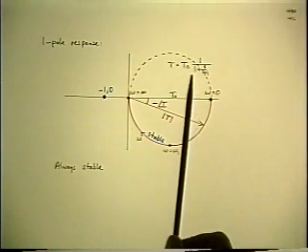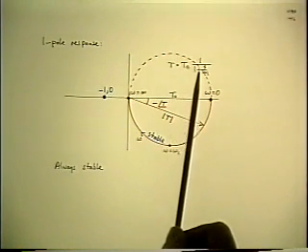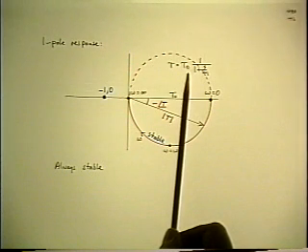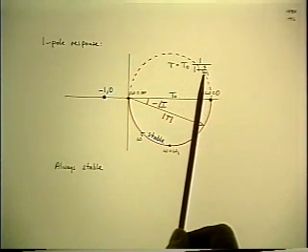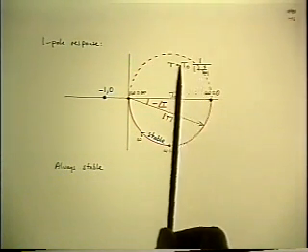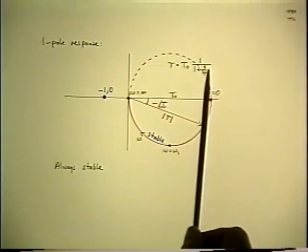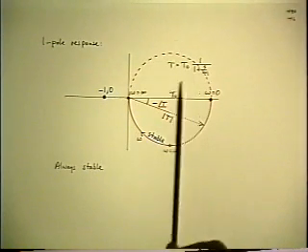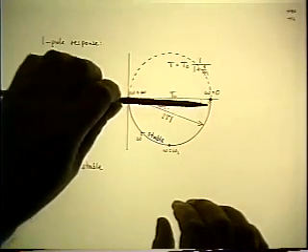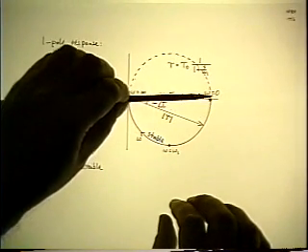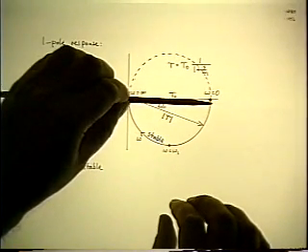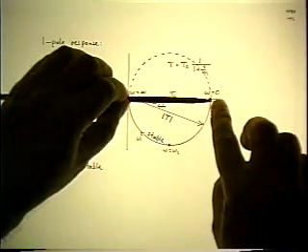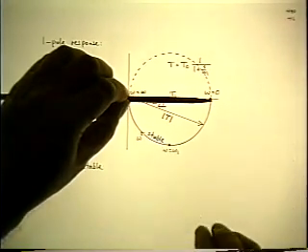Let's take the simplest form of loop gain, which is a flat value t0 and a single pole. The way you make the polar plot is you start with 0 frequency, t equals t0, so you draw a phasor length t0 at 0 degrees to the reference direction. And you label the end of it omega equals 0.